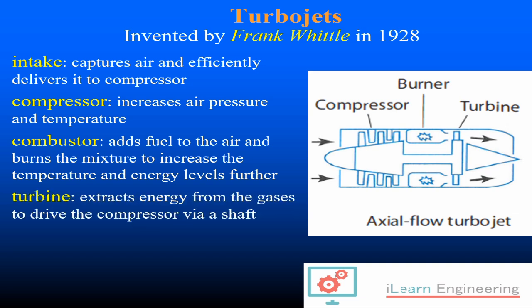The turbine extracts some of that energy from the gas, which drives that central shaft, like we talked about earlier on, which is connected to the compressor. And then the nozzle accelerates. The nozzle is a convergent design, so it's designed to accelerate the gas even further, because as we know from our earlier thrust equation, the velocity of the gas is important.